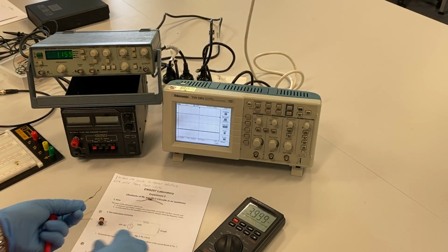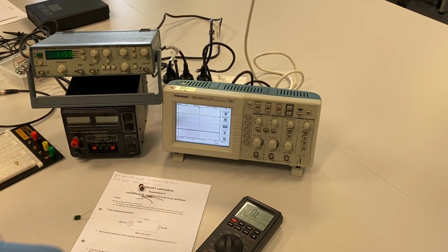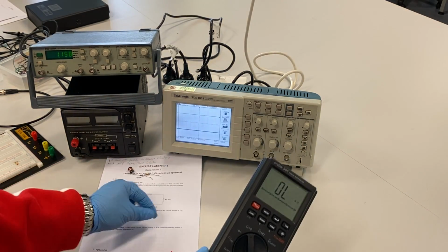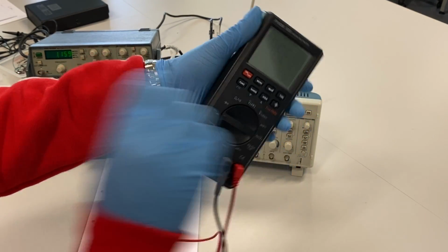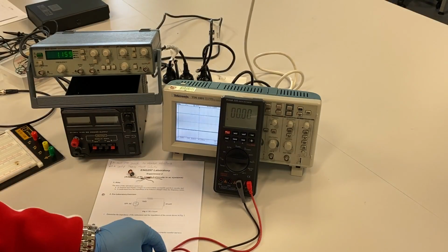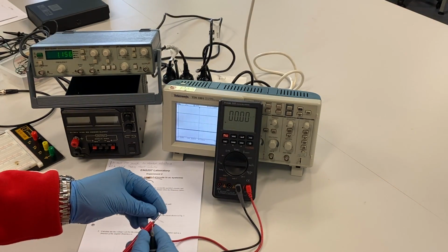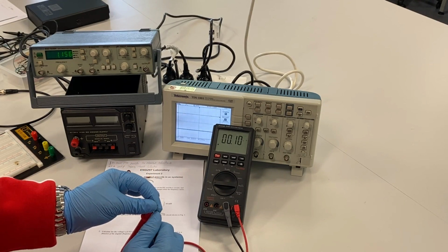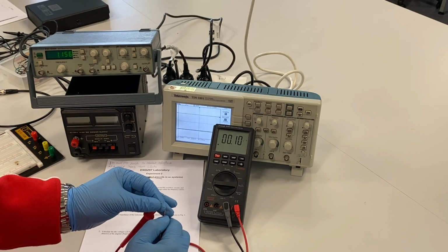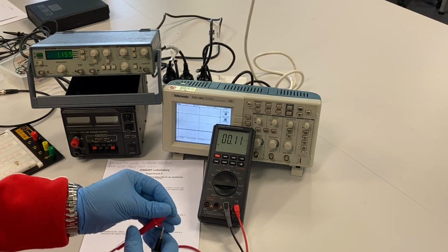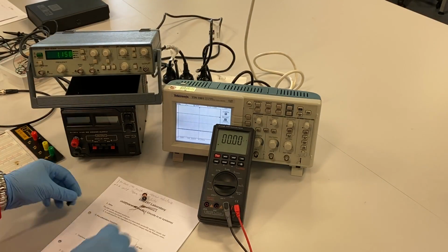Now, I want us to measure the value of the capacitance, right? Like what I said, we leave this one on the voltage measuring side, then we just take the capacitor, but we have to turn this knob to the capacitance side. Yep, up to there. Then let's see if we can display our capacitance, right? It's supposed to be 0.1 microfarad. Let's see that. There we go. Yeah, 0.1 microfarad, 0.10 microfarad. So we're using the correct capacitor, right?